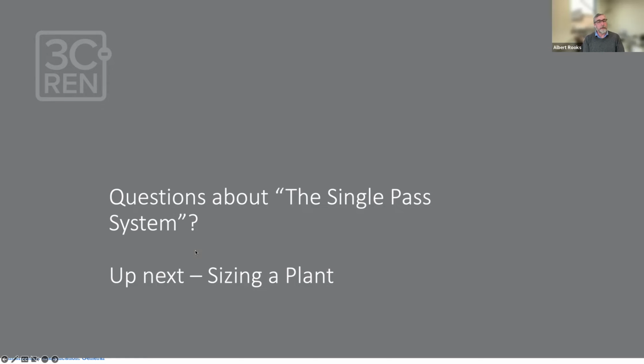Less thinking that heat pumps can't keep up, will run more often. Yeah, so that's when you undersize. I've watched a building get undersized, and when we get into the sizing tools, we're going to assume that the load is going to be served by an amount of primary storage, and that to fill that primary storage with a heat pump, we're going to also assume a duty cycle, because we can't really expect these heat pumps to run 24/7.